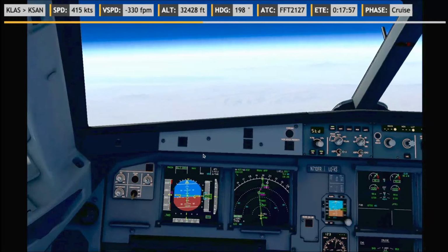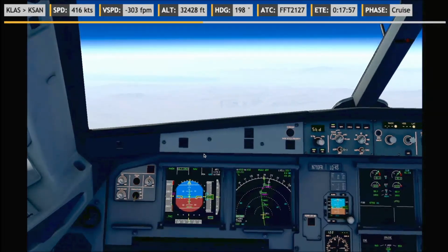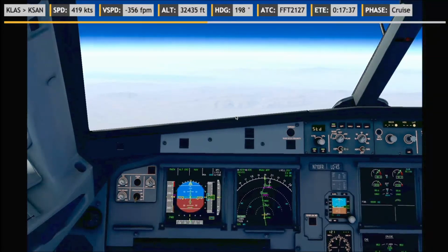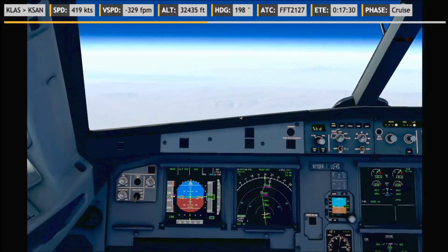And the holding entry is going to be parallel or a teardrop, but I'm going to prefer parallel or whatever the airplane gives me if we get it on automatics before that. On inbound 095 from SARGs and a 5-mile leg. Alright.